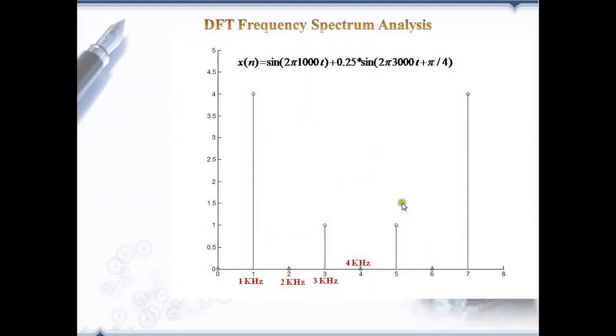Let's get started. This is the spectrum for the example that we have seen in the last episode. We have fed 8 samples to the DFT and got 8 samples at the output, that is from sample index 0 to 7. In general, DFT gets N input samples and outputs N samples. The sample index runs from 0 to N minus 1 at both the input and output.